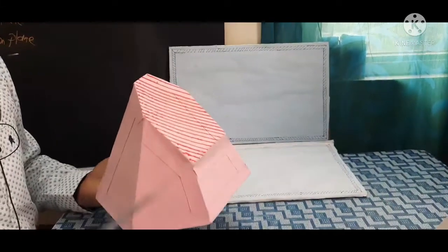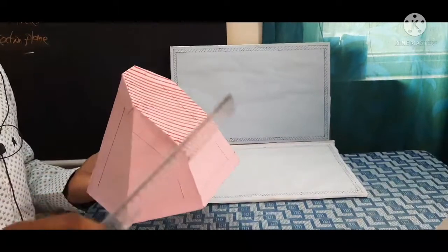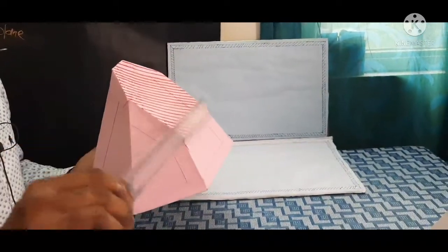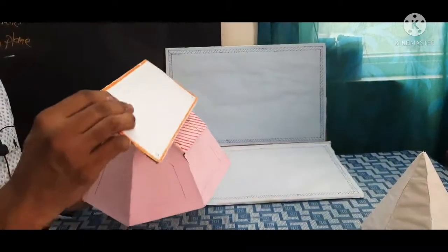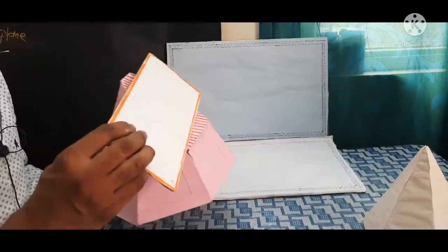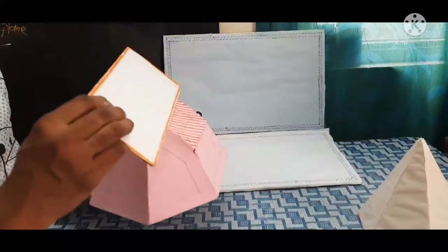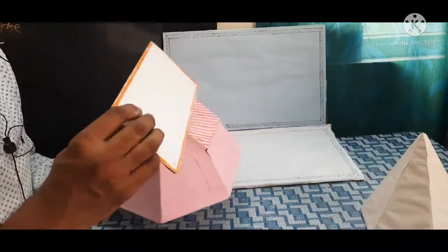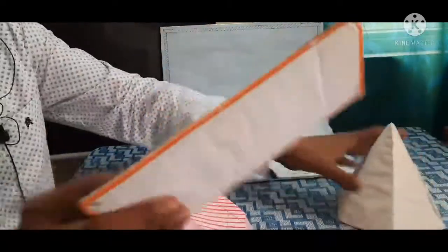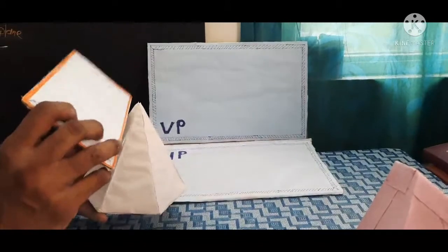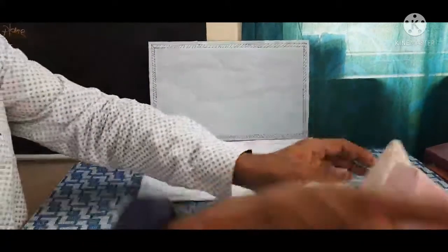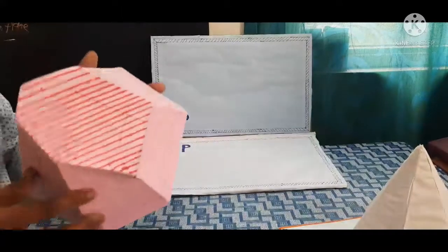Here I cut the previous solid in this direction. I consider one plane. The plane, for this problem, is perpendicular to VP and inclined at some angle to HP. So I am going to cut the solid. What is the solid? Hexagonal pyramid. Before the cut, I keep it in this way. Then some portion is to be removed. The top portion is removed. After removal, I get the object like this.